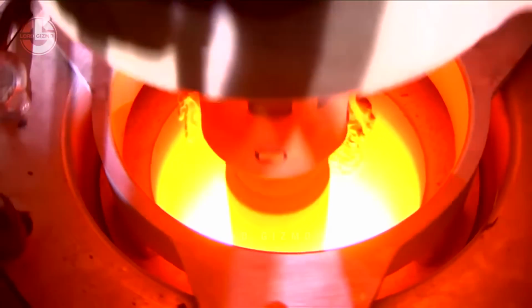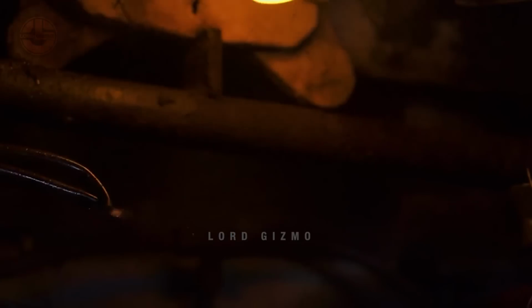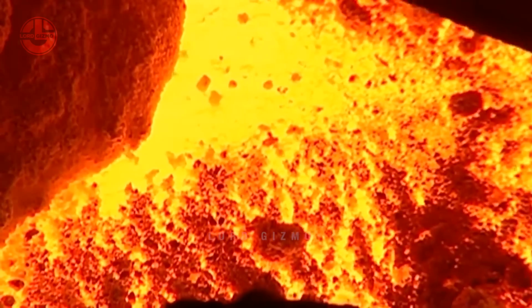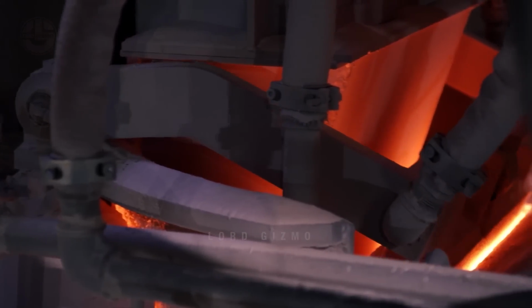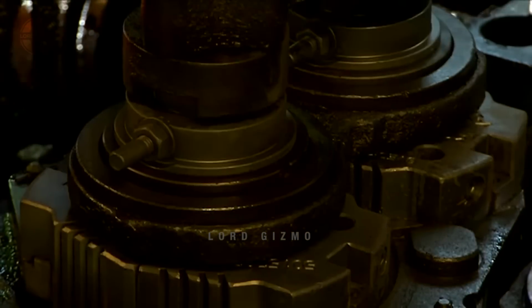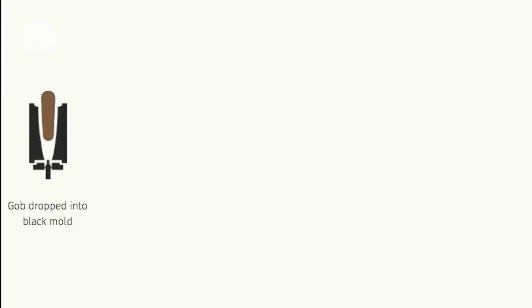The difference in the process starts with the glass forming process. In this process, the molten glass is fed into narrow canals, which are known as feeders. The molten glass, in specific amounts, is allowed to fall through an opening at the bottom of the feeder. This falling molten glass is known as a glass gob, which is poured into a blank mold. The gob adapts to form the neck of the bottle due to its molten state.